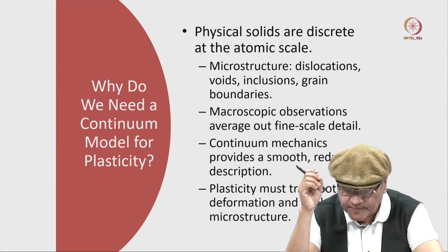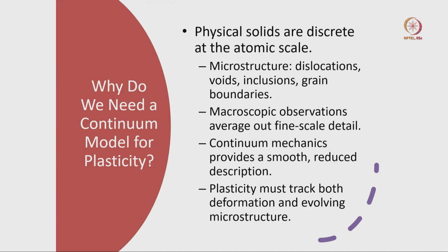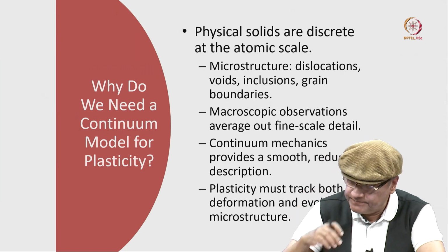So plasticity must track both, unlike elasticity, which you may have already gone through in your earlier courses. Plasticity is not just about the deformation of the body. It is also about the microstructure, how the microstructure evolves. In fact, it co-evolves with the deformation. So it is quite unlike elasticity from this angle.